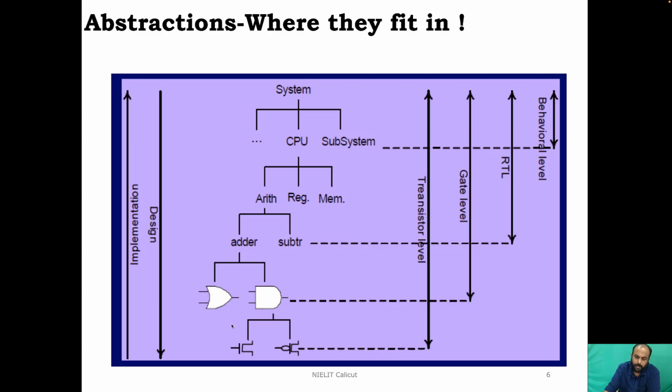Whenever you are working in a product company, most of their products will be reaching maturity. So in that case, they will be having structural descriptions, which is the most foolproof way of taking it to synthesis. The other styles include the RTL way, or say data flow modeling, wherein we are specifically telling how data flows between different components. At the top level, that is at the system level, and often when the algorithm is complex, say a DSP algorithm, when there is a lot of computational complexity involved and it's more algorithmic in nature, we go for behavioral modeling.